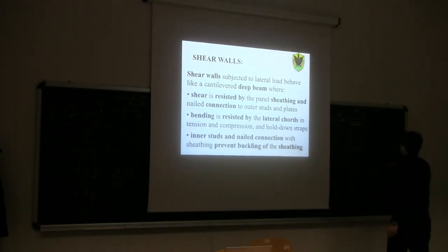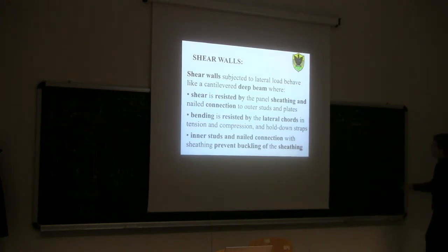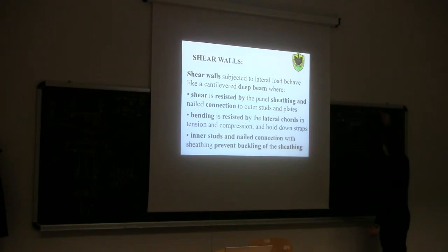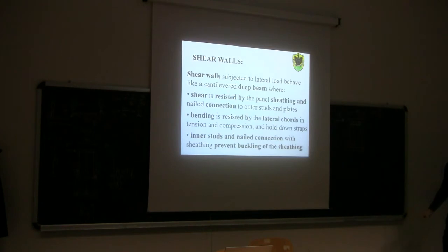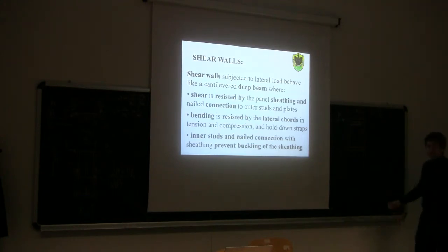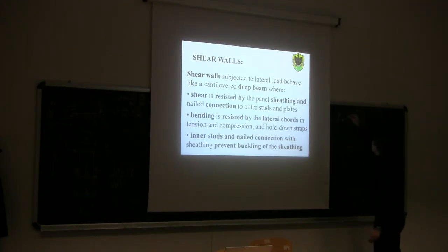So, shear force per unit length, V. V will be F over B. Okay? Shear force per unit length. And we can assume with some simplification that those shear forces per unit length are uniformly distributed along the breadth. If they are uniformly distributed along the breadth, which kind of axial force diagram will we have in our plate?